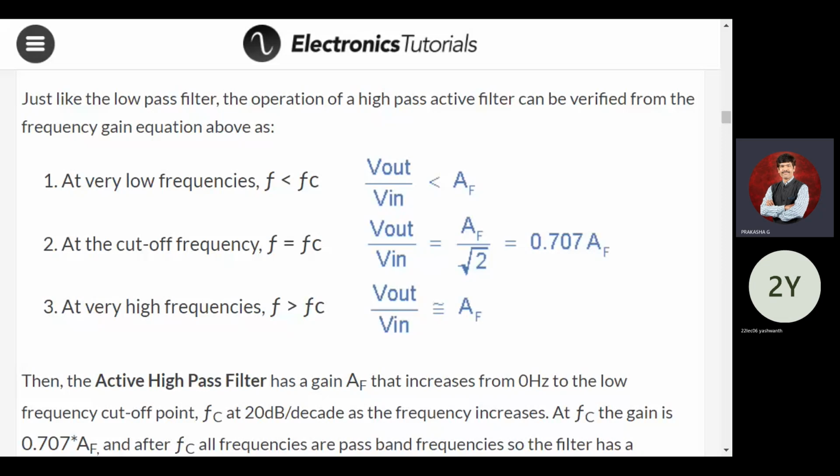numericals also. So here, in a high pass filter, during the low frequency it's a stop band. It will not permit any frequency to reach the amplifier. All the low frequency will be filtered out. Only the high frequency component is going to be given to the op-amp itself. Since there are two sets of filters, instead of 20 dB, we go for 40 dB. We are not going to get the 20 dB, we get the 40 dB cutoff. So it stays in the stop band initially, and once it reaches the cutoff frequency, it goes to the pass band.